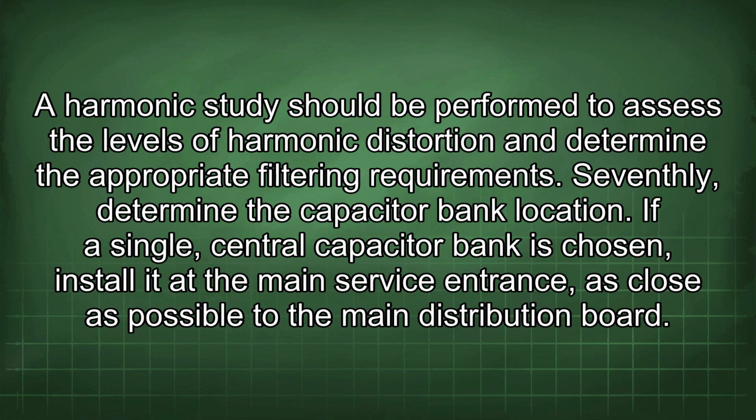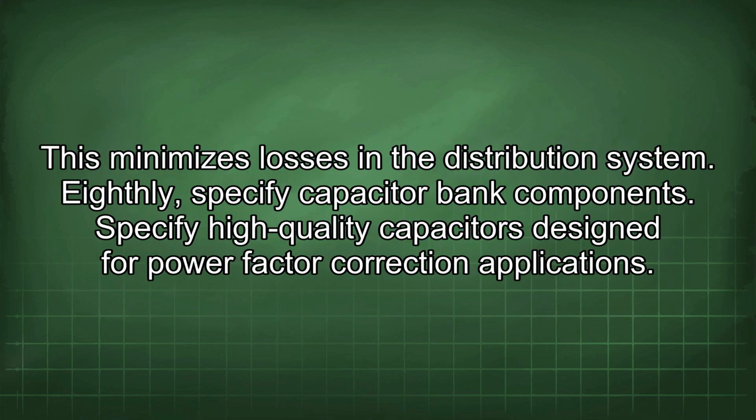Seventhly, determine the capacitor bank location. If a single, central capacitor bank is chosen, install it at the main service entrance, as close as possible to the main distribution board. This minimizes losses in the distribution system.